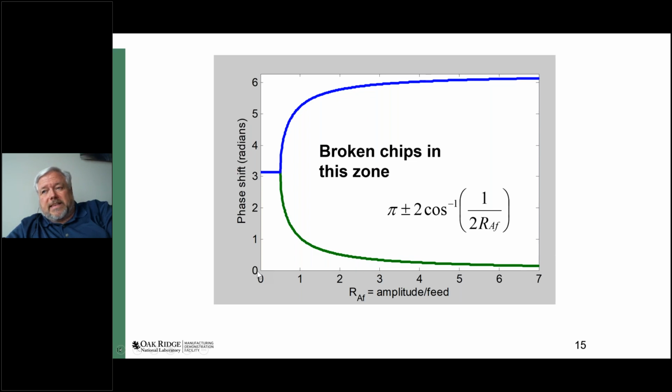So effectively the 0 means that the frequency of the motion is 0, so the tool's not moving, and that looks just like regular turning, right? The top actually means exactly 1 cycle of the motion per revolution, and that means that the wave left on the surface and the motion of the tool are just exactly lined up.